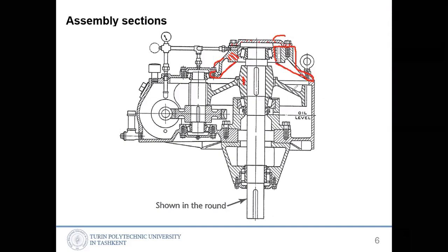Even though both are a similar type, if you have two parts that should be mounted together with a similar material, because those are 2 different parts, you can change the direction of the sectioning, the hatching.